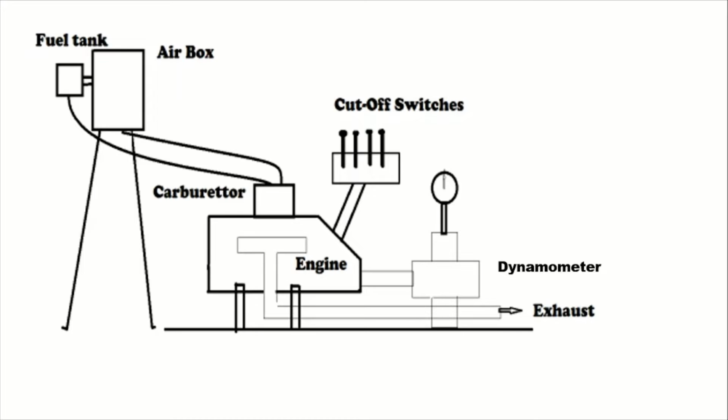This is done to maintain the friction power constant, which is considered to be independent of the load and proportional to the engine speed. The difference in brake power between all cylinders firing and with one cylinder cut off is the IP of the cut-off cylinder, and the summation of the IP of all cylinders then gives the total IP of the engine under test.